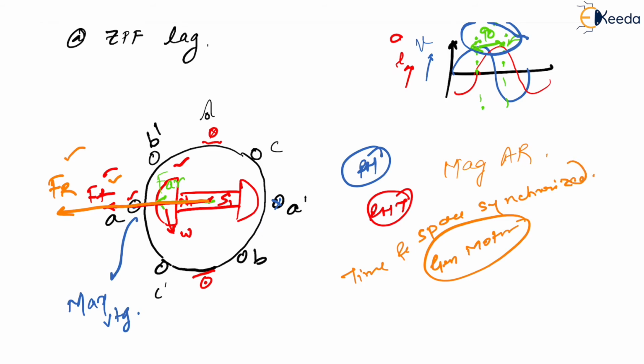That is the reason we can also combine time phasors, time displaced phasors, in our space displaced phasors of MMFs, correct? Which means definitely I can show your induced EMF EF, we can also show ER, and we can also show IA. So let us try to show them on each and every graph.